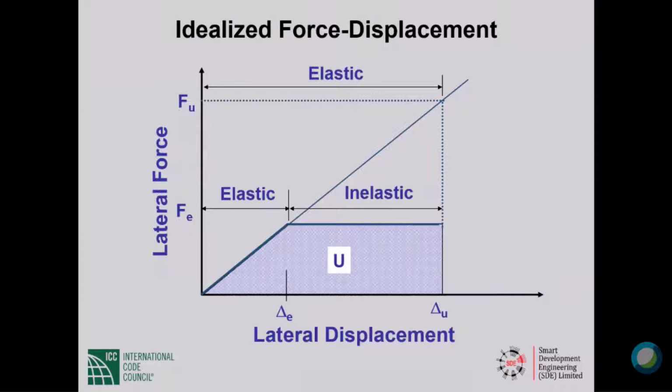And that's what the materials chapters of the code are about. So my message to you, and this is something you always have to remember: earthquake design, seismic design, however you want to say it, is a two-part affair. We design for the forces that are given, in your case, in Part 2, Chapter 6 of BNBC 2020. But then you also have to detail the structural members and the joints as required by the detailing chapter. It has detailing for concrete buildings, steel buildings, and so forth.